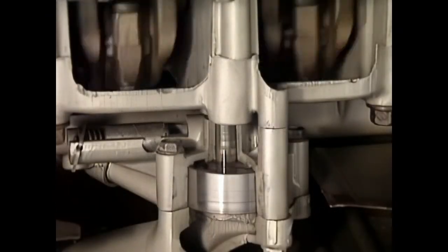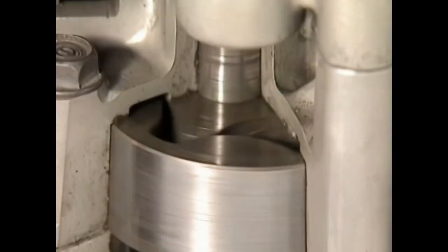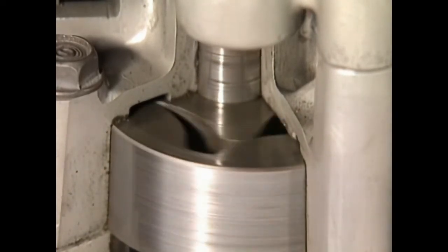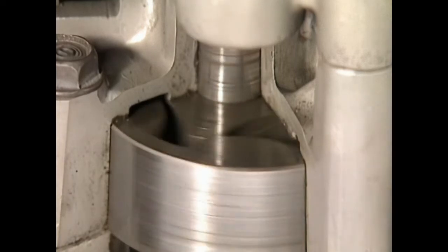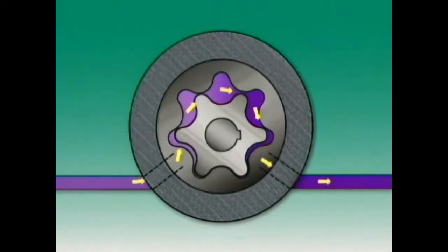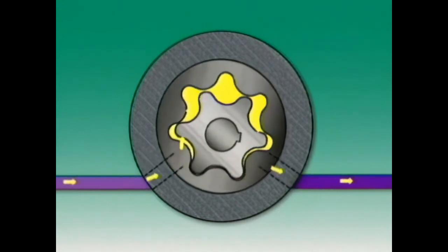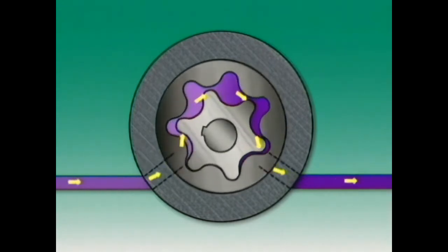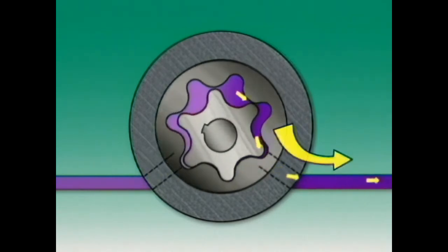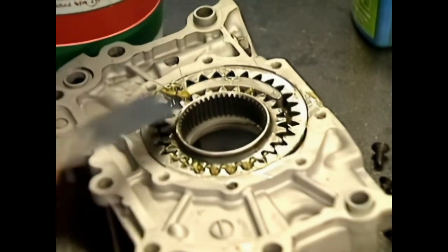In a rotor-type oil pump, an inner rotor drives an outer one. As they turn, the volume between them increases. This larger volume lowers the pressure at the pump inlet. Outside atmospheric pressure is then higher. This forces oil into the pump, and it fills the spaces between the rotor lobes. As the lobes of the inner rotor move into the spaces in the outer rotor, oil is squeezed out through the outlet. The crescent pump uses a similar principle.